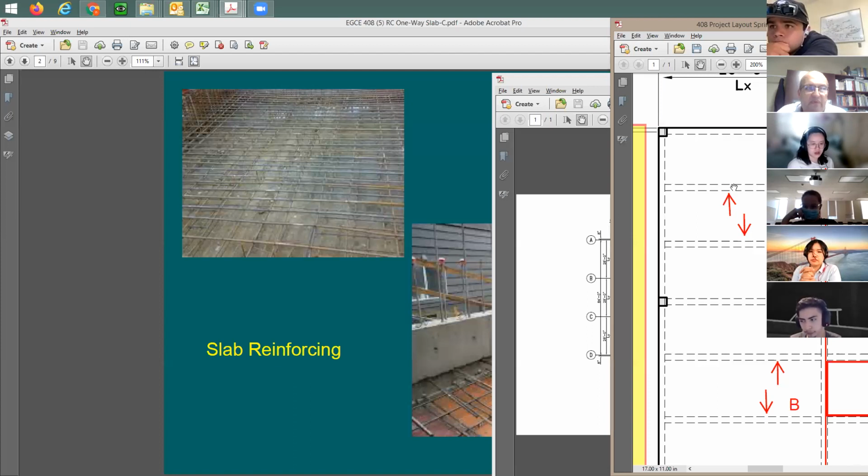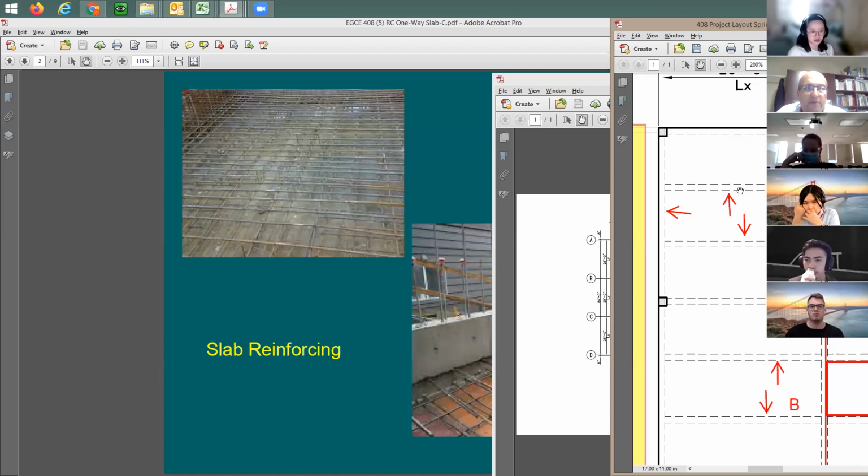So load is going to be moving to this beam and that beam, meaning there is no direct load coming from the slab to this beam or to this beam, just simply because of the aspect ratio of the slab, the width to length ratio. Also, nothing is coming to this beam here or to this girder. Load first goes to these two beams and then it goes back to the girder, because this girder here supports these two beams.